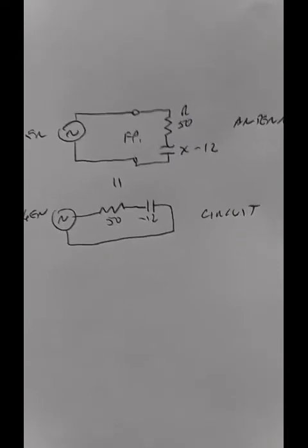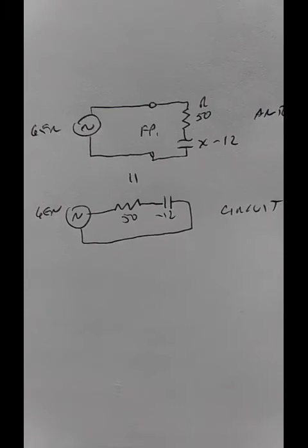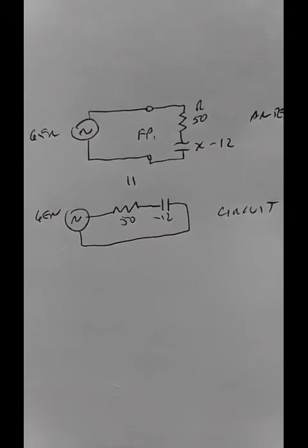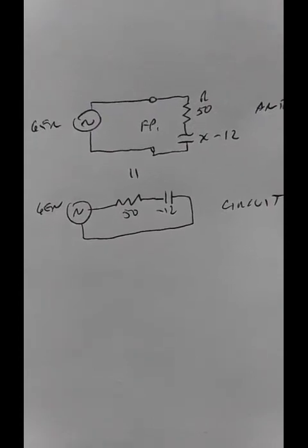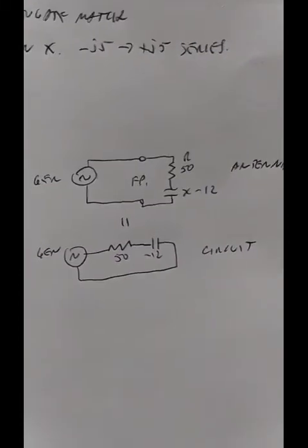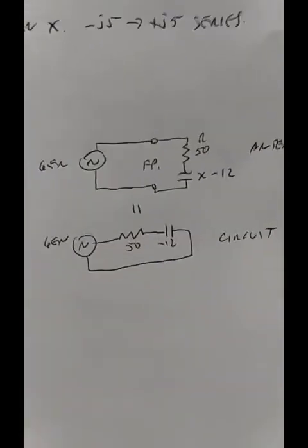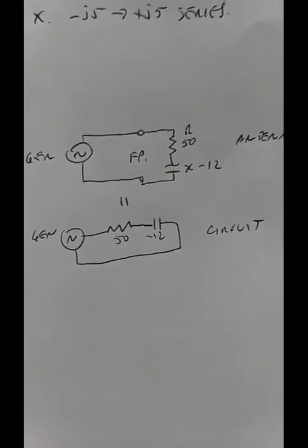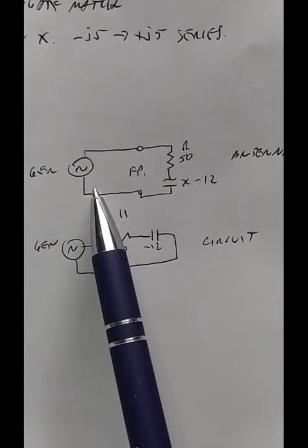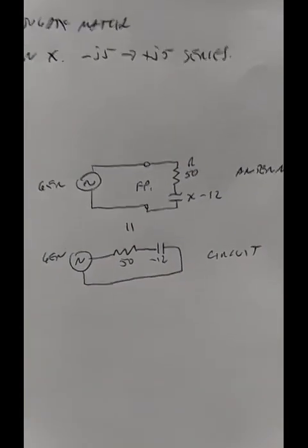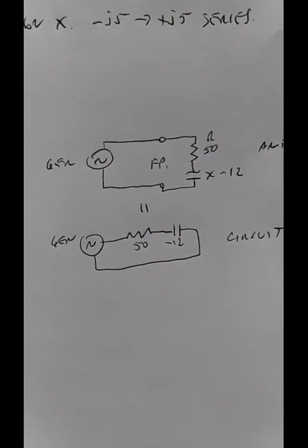As I said before, antennas are tuned. Antennas are electrical mechanical devices. They are tuned by their length, wire diameter, height above ground, location with other objects, on and on and on. Absolutely nothing is done here. Absolutely nothing is going to change the nature of that antenna. Does putting an inductor here change the length of the dipole arm? No. It will not change the antenna tuning.